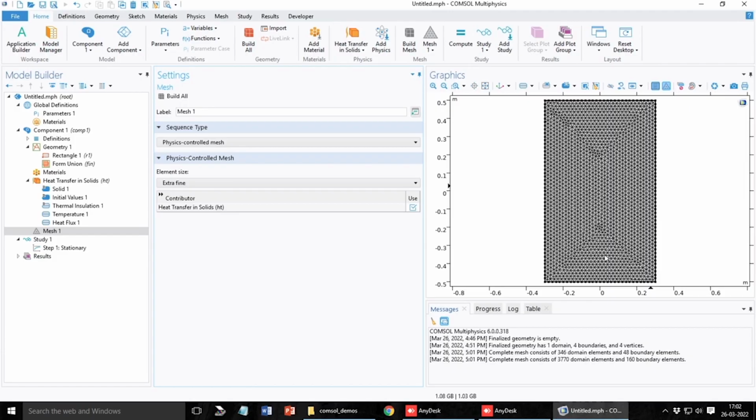If we work on a problem of fluid flow, where there is a strong gradient near the no slip walls, generally the mesh can be more refined there, right. By default the software will be able to generate that. But even if you are not happy with the software generated mesh, you can go for the user controlled mesh, but for beginners this is slightly more complicated, because you have to select a lot of mesh parameters, right. And then of course, you can have boundary layer mesh, and different refinements at different zones of the mesh, right.